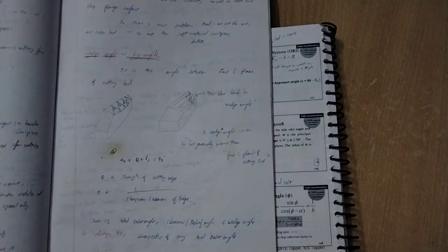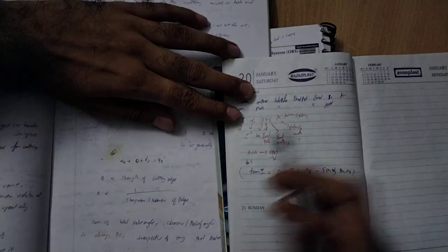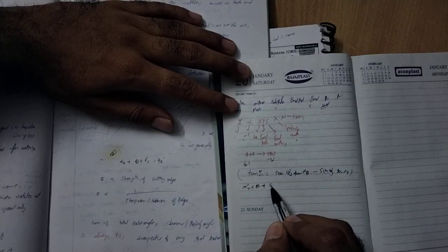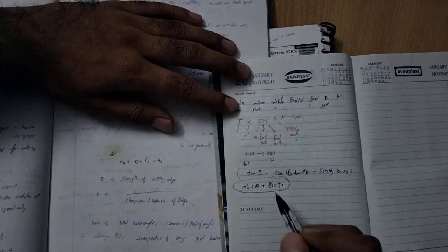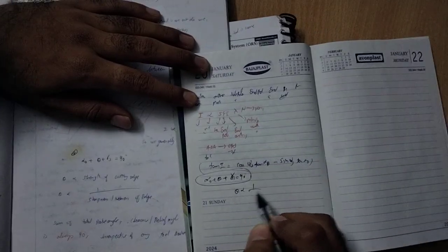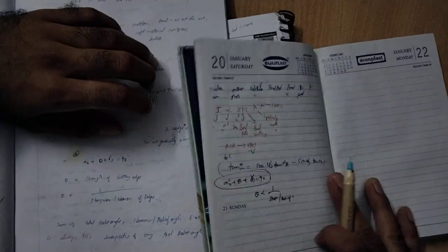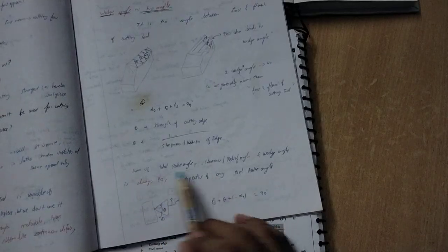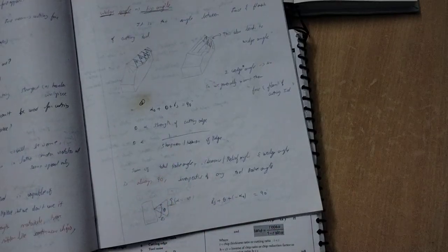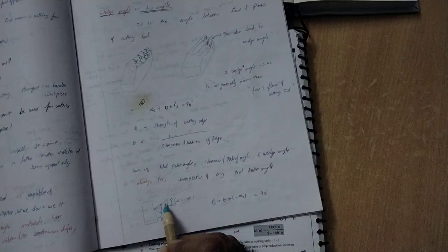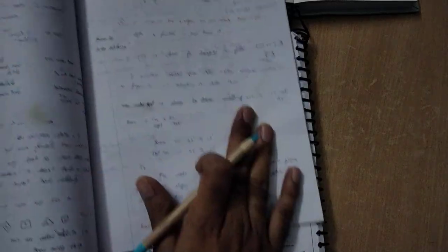So you can see this entire thing will be orthogonal rake angle plus wedge angle or lip angle plus the end side relief angle, equal to 90 degrees. Next, theta is directly proportional to 1 by the sharpness or keenness of the edge. Each and every time, the sum of the entire thing will be 90 degrees. So you should not be confused.